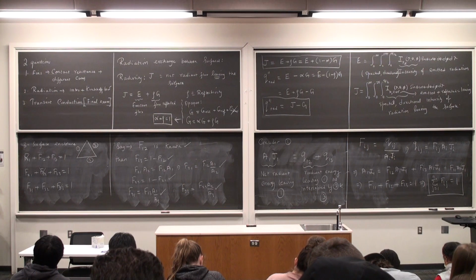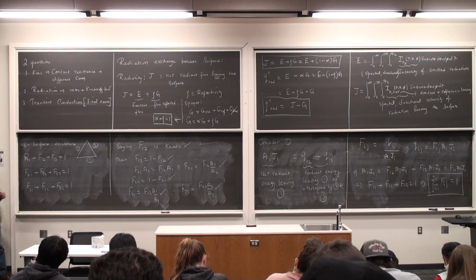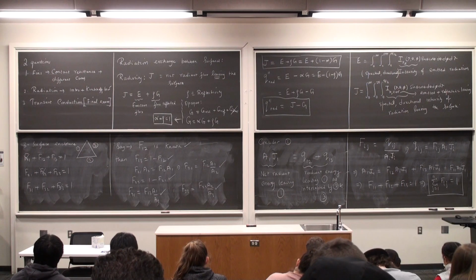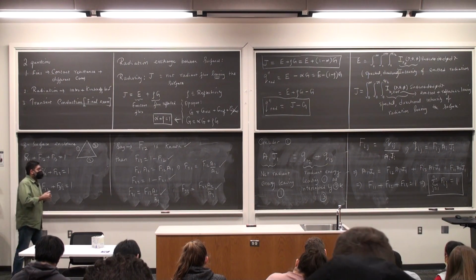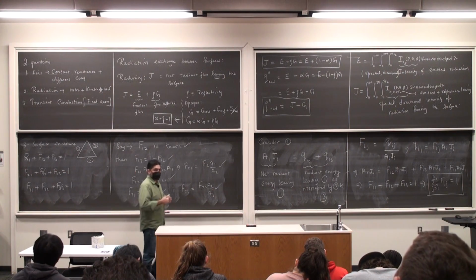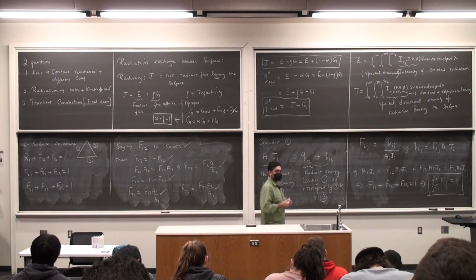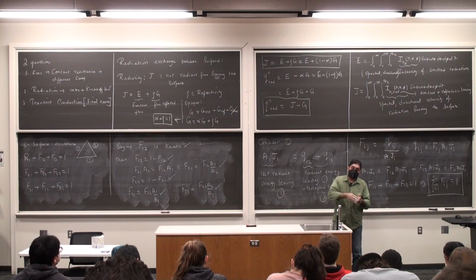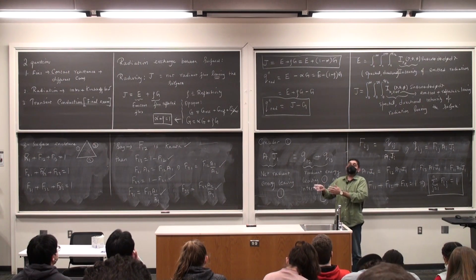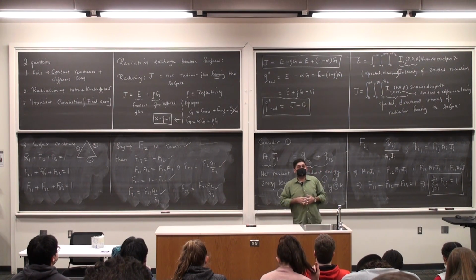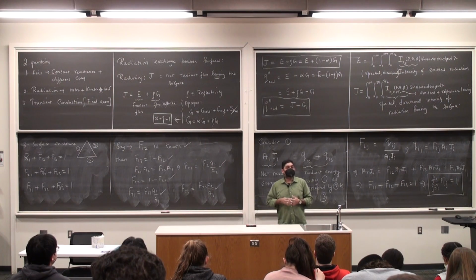To know just one of them for multi-surface heat transfer. And that is the powerfulness of what you're doing here. But this is all under the umbrella that the surfaces are diffuse. Okay, that's something to keep in mind. Which is why we went into Kirchhoff's law to say that, okay, if a surface is diffuse, what's the upshot? The absorptivity on a spectral level is the same as the emissivity on a spectral level.